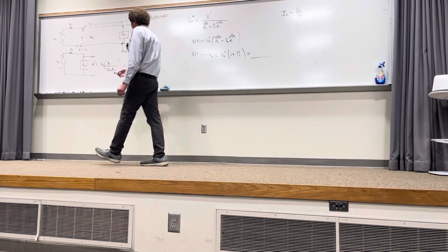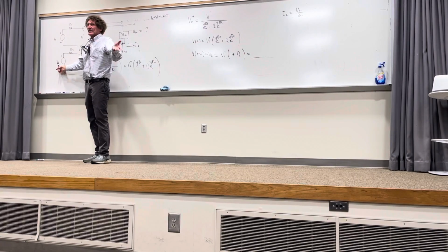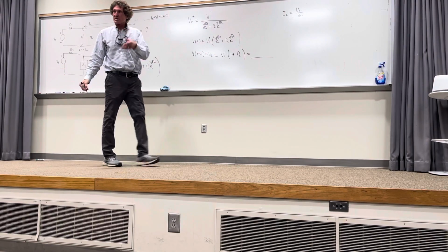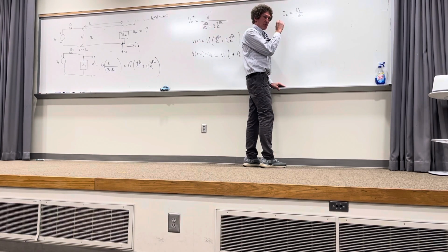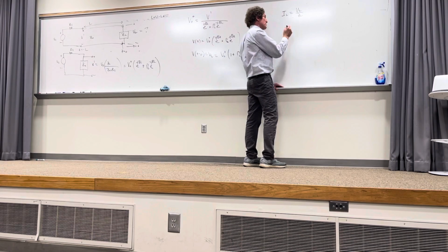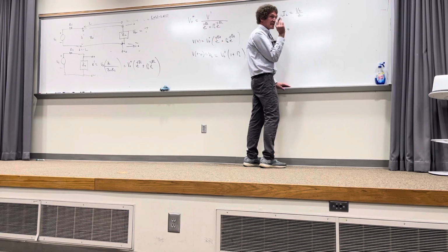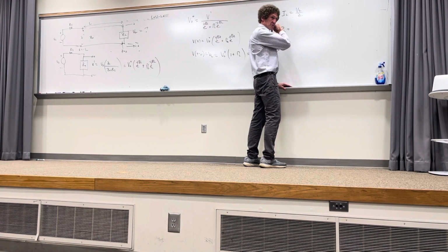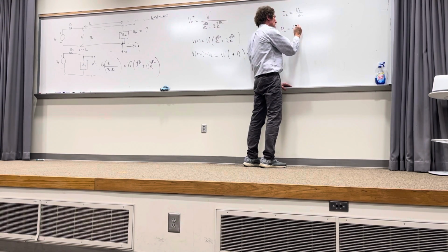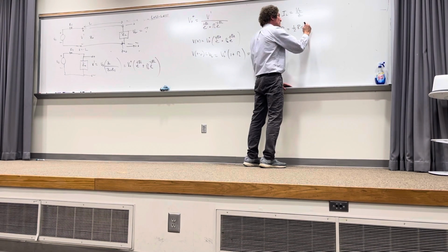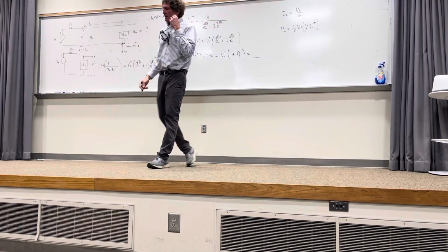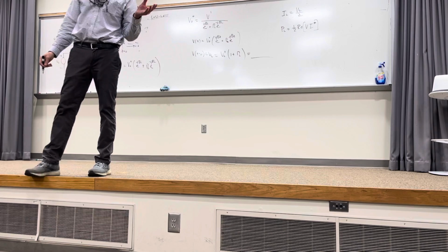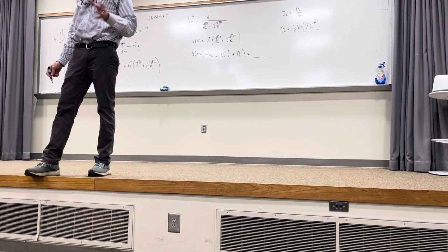Remember, these are phasors. This represents like 10 at an angle of 0 degrees kind of thing. And it's a peak voltage. So how do you get power? Back from your circuits work. VI conjugate? Well, yes, but this is not RMS voltage and current. These are peaks. So what is it? P at the load would be, technically, if we're using peak values for voltage as the driver, 1/2 times the real part of V times I conjugate. Now the total power, V times I conjugate, has the real power in it, but it also has an imaginary or reactive power.